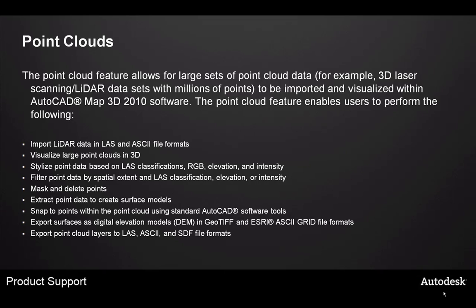It enables users to perform things like importing certain types of LiDAR data, doing visualization of the point clouds in 3D, stylizing the point data, filtering the point data, masking and deleting points, extracting the data to create surface models, snapping to points within the PointCloud tool using your standard AutoCAD software tools, exporting the surfaces, as well as exporting the point cloud layers.